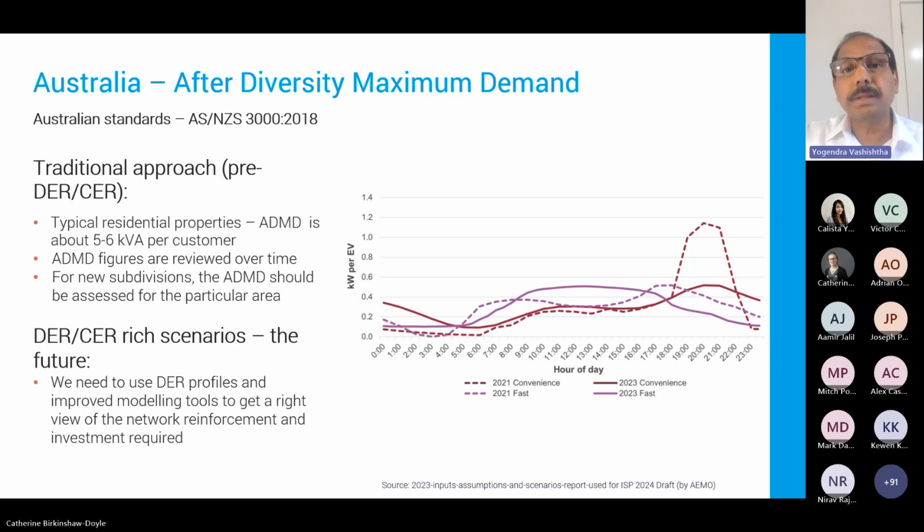Although it has EVs under the load table, it classifies EVs based on, say, 5 dwellings or more than that. And it says if it is up to 5 dwellings, just take the 100% load, that kind of static definition is still there.